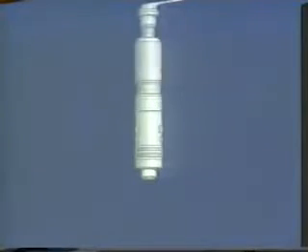The Camco Type M lock mandrel is designed for the W1 nipple. The running tool designed to selectively run the M-lock mandrel is the W1 running tool. The M-lock is pinned to the running tool with 2 tangential shear pins, which pin the housing of the running tool to the dog housing of the lock mandrel.